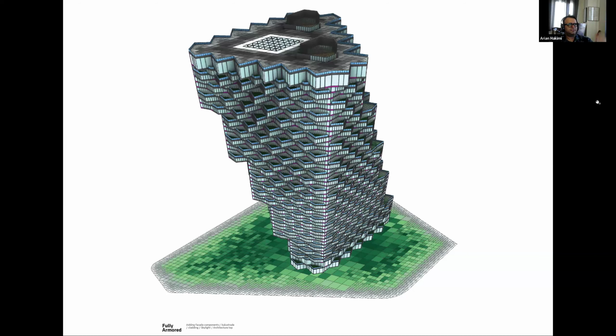And this is how it looks, adding all the parts. As you can see, the extruded balconies, the extruded or pleated terraces, are acting as a self-shading mass, which is a very performative or functional use, in the sense that we are in a very hot and dry climate in Iran. So using shade as a main element to cool the building could be very beneficial in order to have a lower energy impact on the building itself.